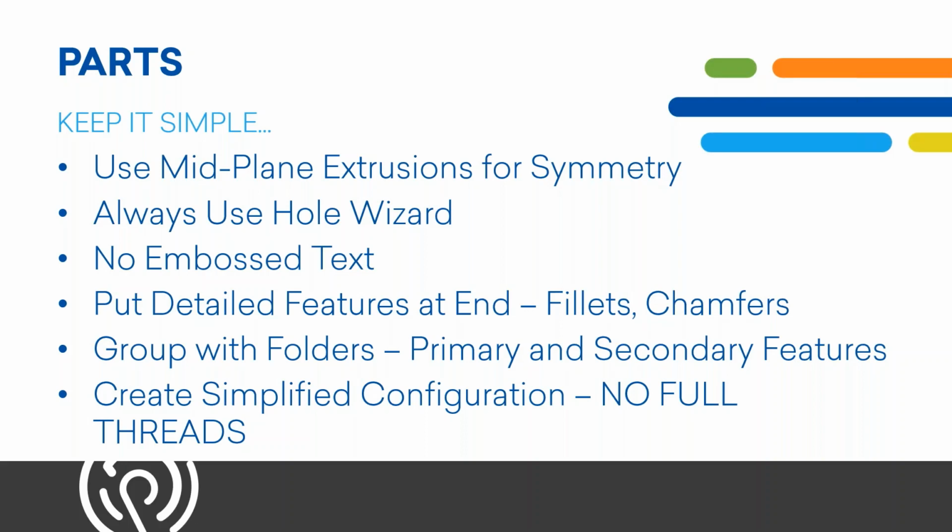The file size will be smaller. The same goes for symmetrical extrusions, whether you can do that mid-plane extrusion. That's just going to be good practice. That's a good design intent modeling practice to follow. And we'll talk a little bit about how it saves you ever so much on every little additional subtraction to your processing. Hole Wizard, if you haven't used that, we recommend that.